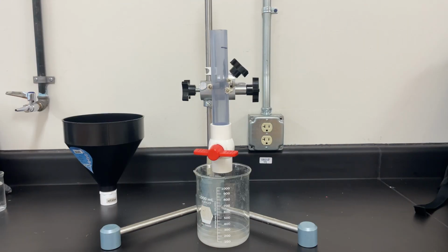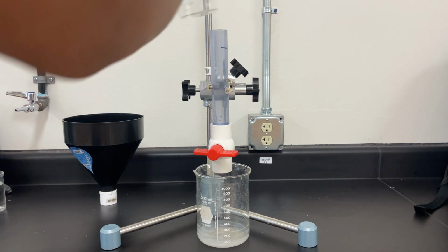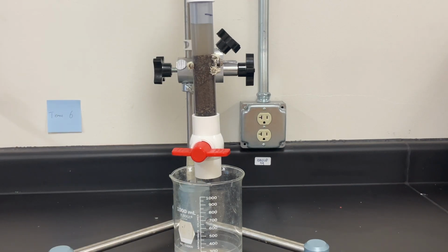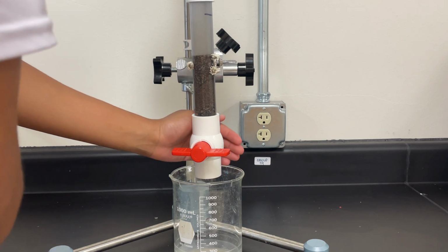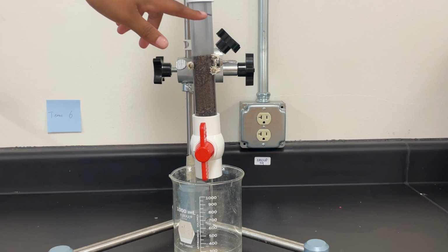When you are all building your filters, there are certain steps that you will need to follow. The first most important step is loading your filter with water. So we're going to add about 50 milliliters of water into our column. Then we'll add our media in whatever chosen order you all decide. Notice how dirty our water is after we added the media to the filter. So we have to wash out our system with about 200 milliliters of clean water. We've added that to our system, and now we're just going to allow it to filter through until it reaches this line here.